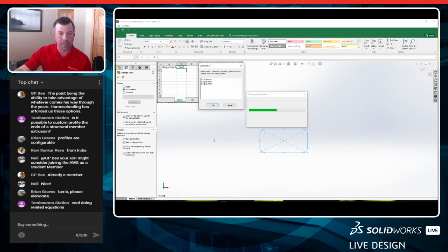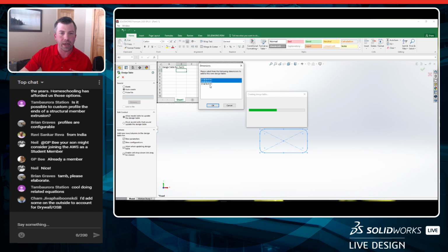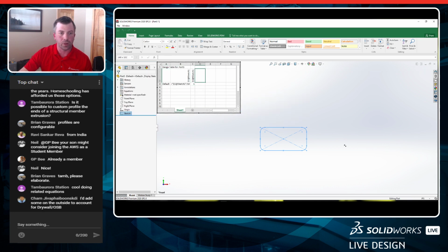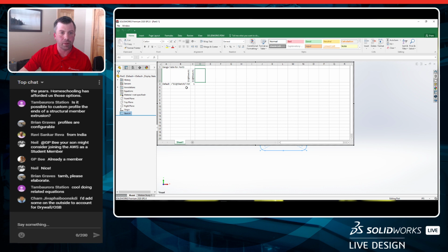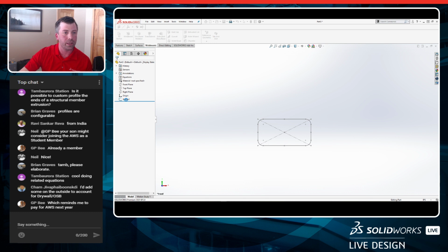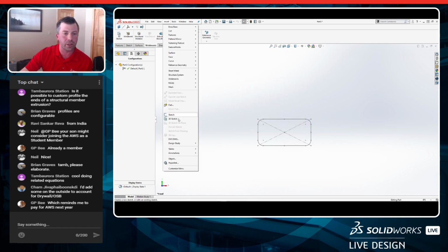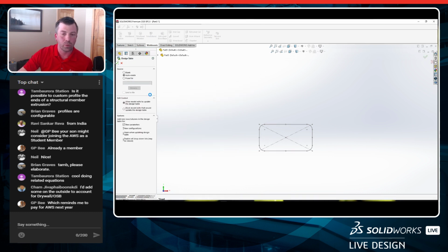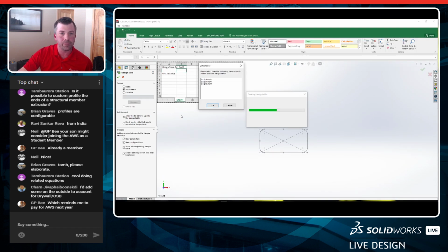So in this case, I've got dimension 1, which was that height, width, and I don't need that radius because that was an equation. So we'll just bring those in. Cool, that looks good. Now we can come through. Actually, let's go back. I'll show you that one more time because I want to auto create and grab the right dimensions. We'll grab everything. So insert, table, design table, the auto create functionality. We'll pull in the dimensions for you. Let's grab all three so I can get the right length, width, height.